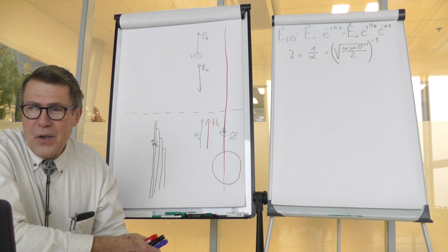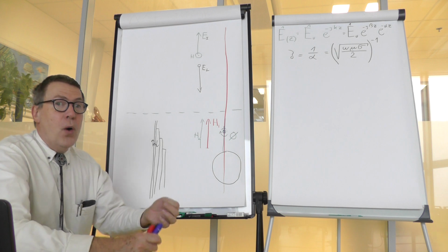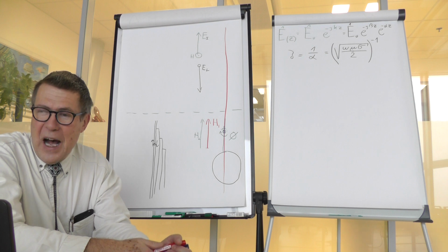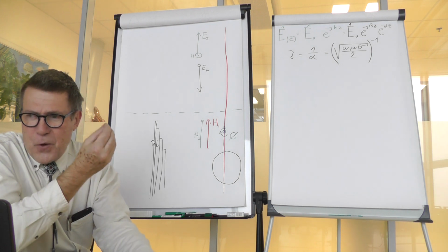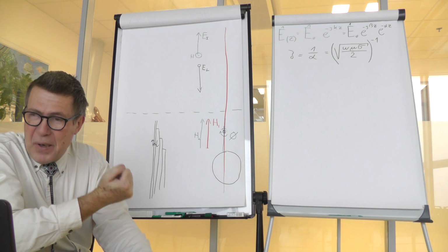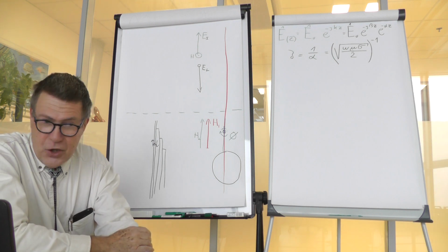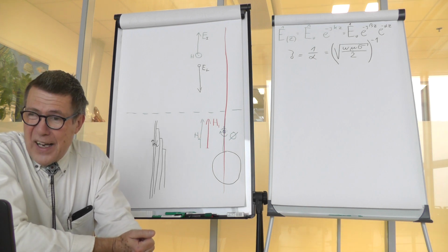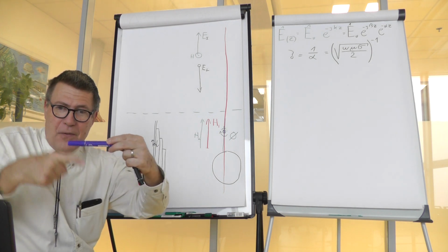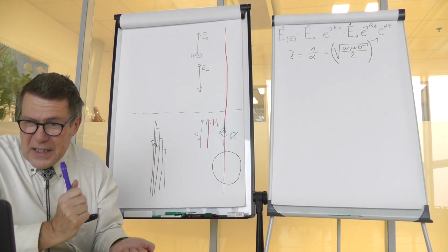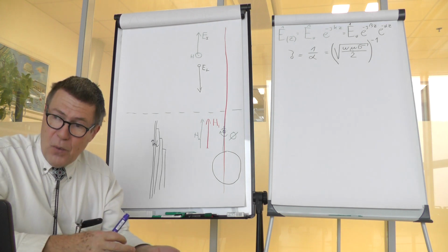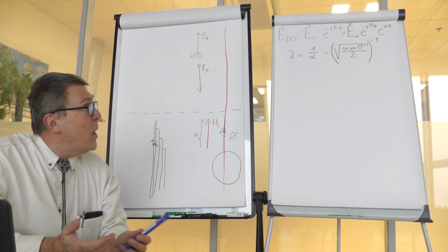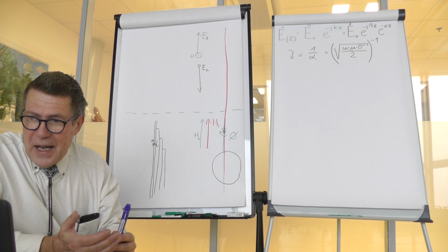For example, if you have ever designed and built your own radio receiver, it's quite common that you have the RF part somewhere from the antenna to the first amplifying stage, and you have to have there, for example, a ferrite antenna, which is a stick of ferrite with several loops on it. And now it's quite important to have low losses, otherwise you increase your noise figure. So what is available there?